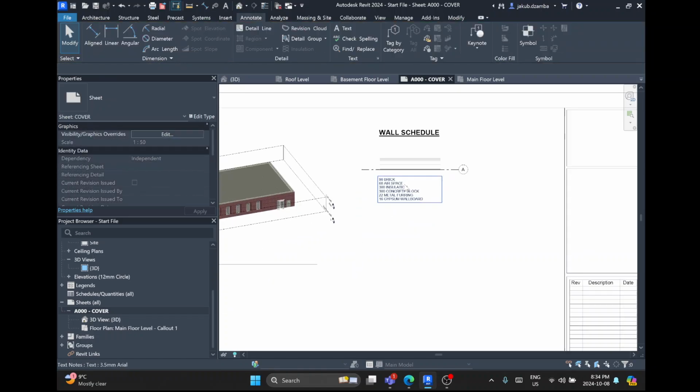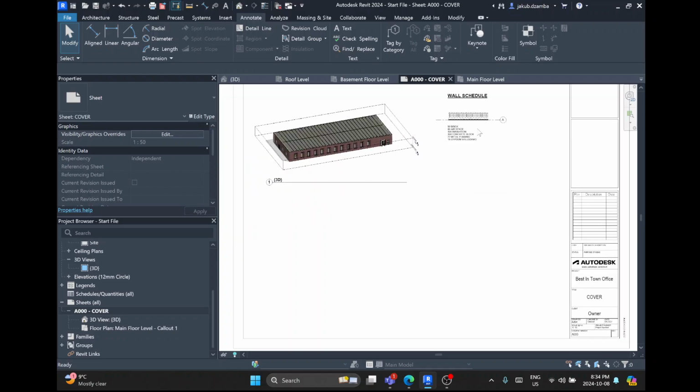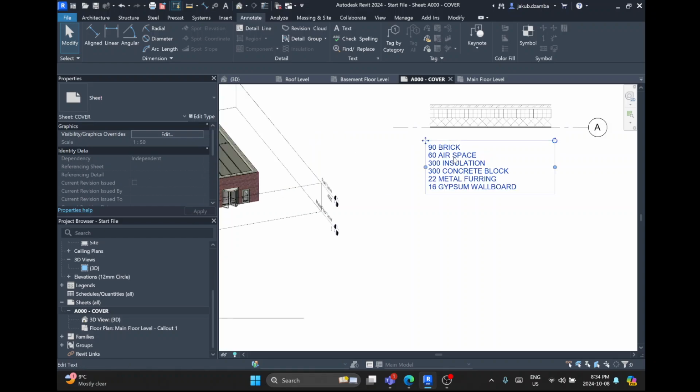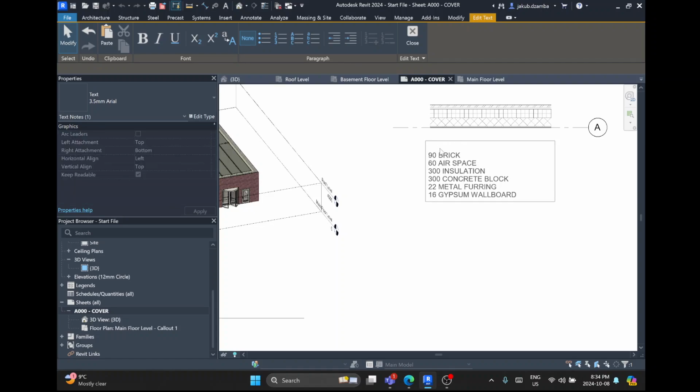This is how we could create a wall schedule. And so you can, oh, and I should probably put in a title for it. So this is, we're calling it exterior wall type 1, I think. So EW1. And that I could also format a little bit. Not italics, bold. And underline, sure, why not? Exterior wall 1, EW1.